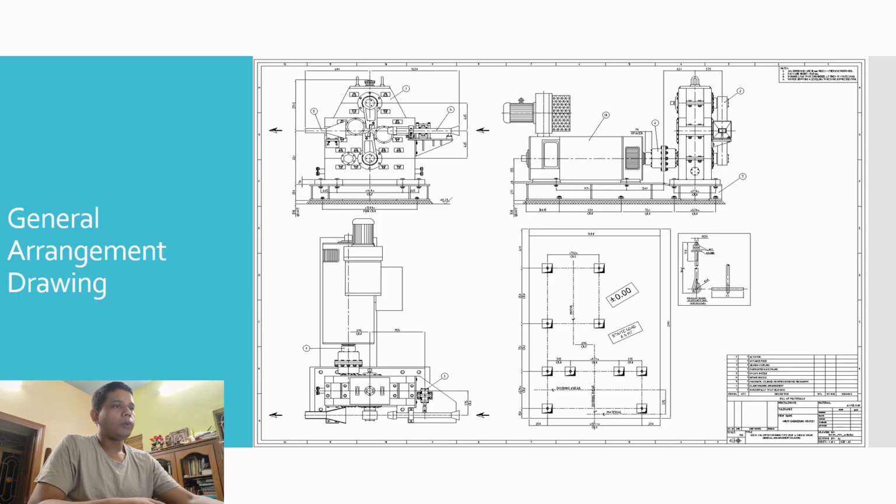It is formed with a gearbox coupled with an AC motor by a geared coupling, which is fixed to the motor shaft along with a distance piece, and the entire arrangement is seated over a fabricated base frame, and this entire structure has been erected over a foundation on grouting.